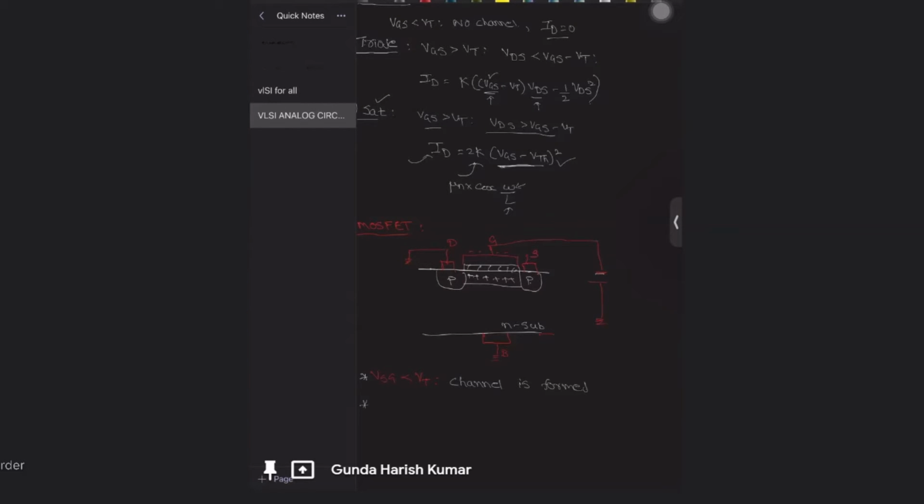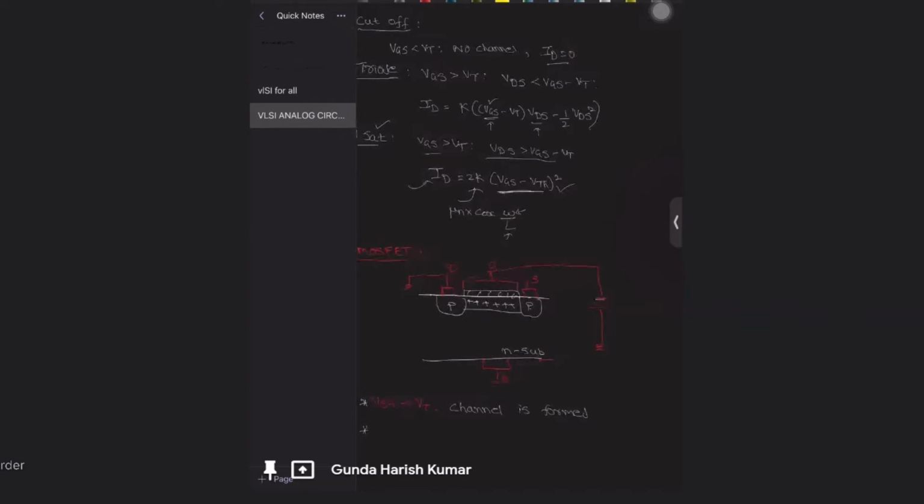Sir, I think ID in the saturation region is equal to K by 2 into VGS minus VT whole square. Sir, here K by 2 will come instead of 2K.